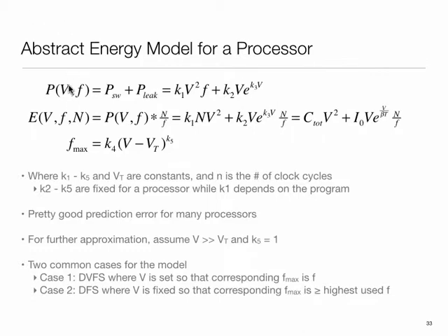Now, not every pair of voltage and frequency is possible. That is, if I give a voltage, there is going to be a corresponding maximum frequency possible. But you can always operate at a lower frequency if you so choose. So in early days, there were systems where voltage could not be changed, but frequency could be changed. So you could basically lower the frequency, but not affect the voltage. Did they serve a purpose? Let's say I give you a system where voltage cannot be changed. It is fixed at the board level, but frequency you can change. So is there any benefit to lowering the frequency?